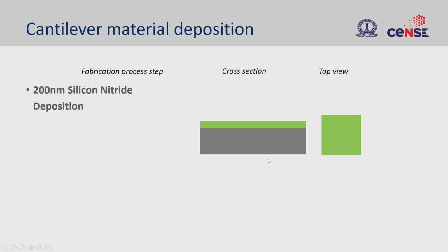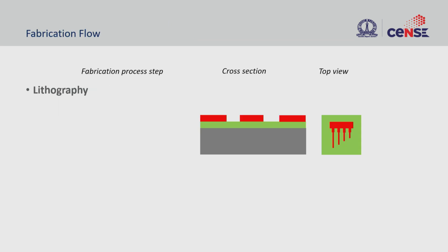Once the deposition is done, we are going to use the silicon nitride that we achieved using the LPCVD process and start doing patterning. The next step is lithographic patterning, where we are going to coat a thin layer of photoresist and transfer the pattern, right? So we transfer the pattern that we want onto this photoresist, and later transfer this pattern into the silicon nitride layer. The first step in lithography is to transfer the pattern onto the soft mask here, and we will see that demo shortly.